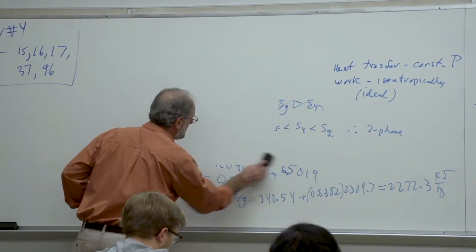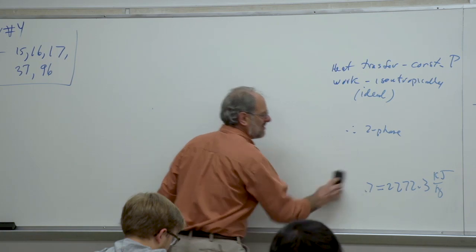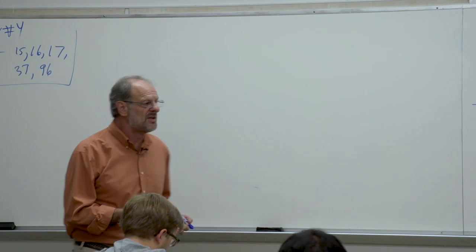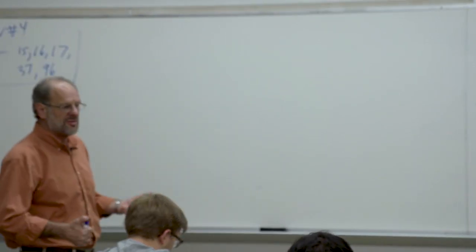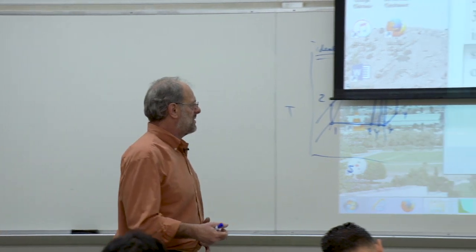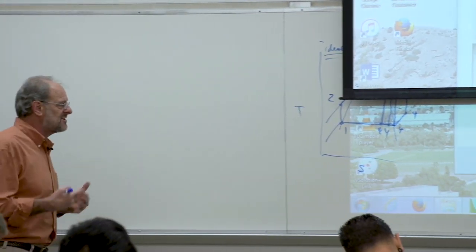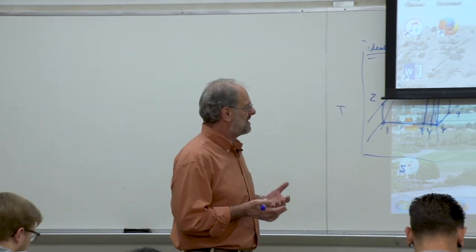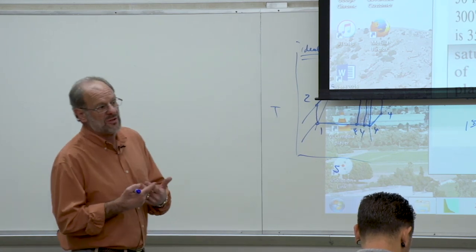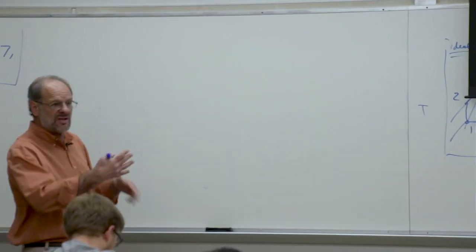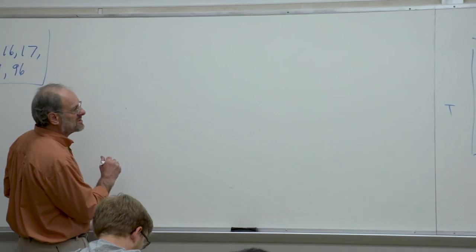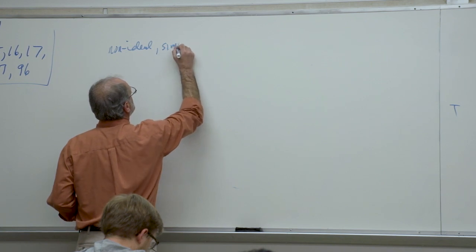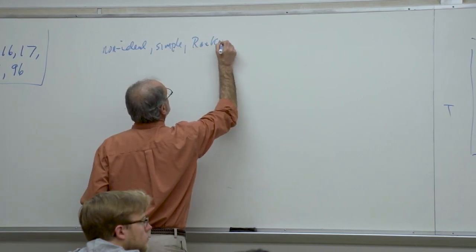At this point, what we need to do is look at the non-ideal cycle. So certainly this cycle has some merit, but it's not particularly realistic. We know that there's going to be friction losses in the real world anyway. We know there's going to be heat transfer losses in the real world anyway within the turbine or within the pump. So we really have to identify those losses, and the way we do it is through isentropic efficiencies, just like we've done for our other cycles, our Brayton cycle specifically. So let's now look then at the non-ideal, but still simple Rankine cycle.